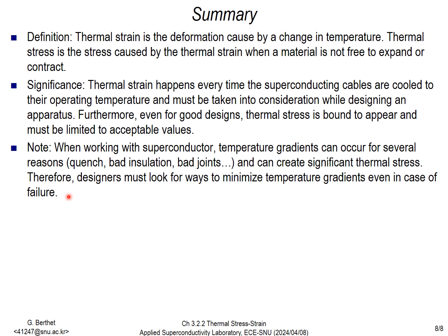As a side note, in superconductors, temperature gradients can occur for several reasons: quench, bad insulation, bad joints, and can create significant thermal stress. Therefore, designers must look for ways to minimize temperature gradients even in case of failure.